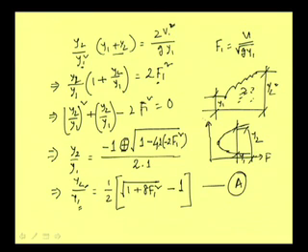This is specific force, this is depth y, and this depth is of course critical. This is the critical depth yc, and one of the depths is in the subcritical region. This depth y2 is greater than the critical depth, and this initial depth is lower than the critical depth. So, that we need to know. y1 is called the initial depth, y2 is called the sequent depth, and together y1 and y2 we call the sequent depths of the hydraulic jump. They are also called conjugate depths.